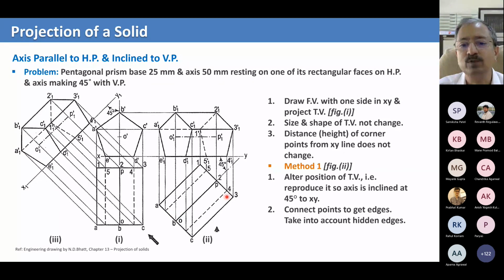Ignore the dashed lines for the moment. The two rectangles on two sides of the middle line are projections of the top two faces. And the dashed line which you see, and the outermost line, represent the projection of this face.